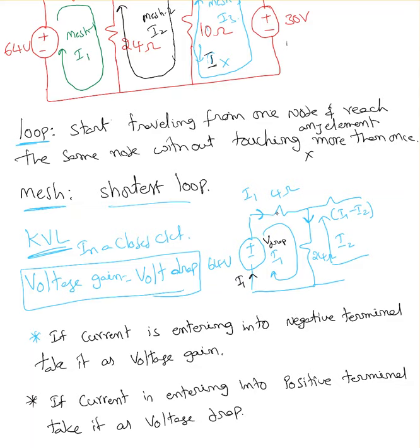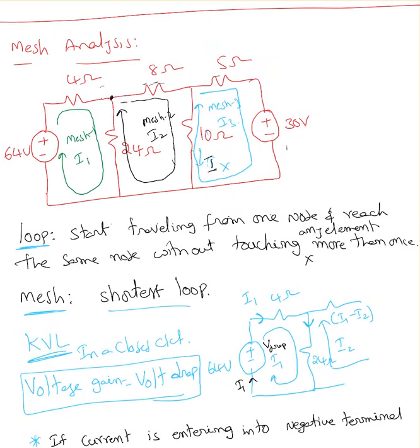Now for the resistor, I don't have a positive sign or negative sign. So what we need to do is assign positive and negative signs for each and every element. When I draw the loop current, basically I start walking from there and reach the same node, passing through all these three elements. The resistor always consumes energy. Basically it consumes electrical energy and gives you back either heat energy or light energy. It always consumes the electrical energy.